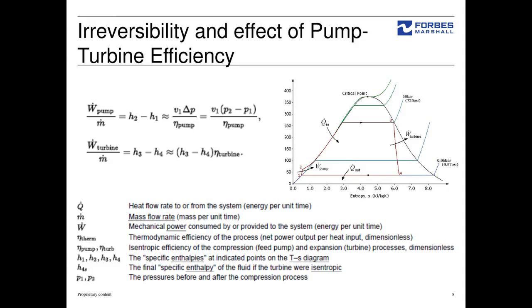So if you take an ideal Rankine cycle, it is quite easy to understand. But as I said before, no cycle can be ideal in all respects. So even in Rankine cycle, as we discussed in past, process 1 to 2, which is a pumping of your feed water, is supposed to be an isentropic process and supposed to be a straight vertical line on your TS chart, but as you can see it slightly bends to the right side. And this is mainly because of irreversibilities and inefficiencies within the pump.